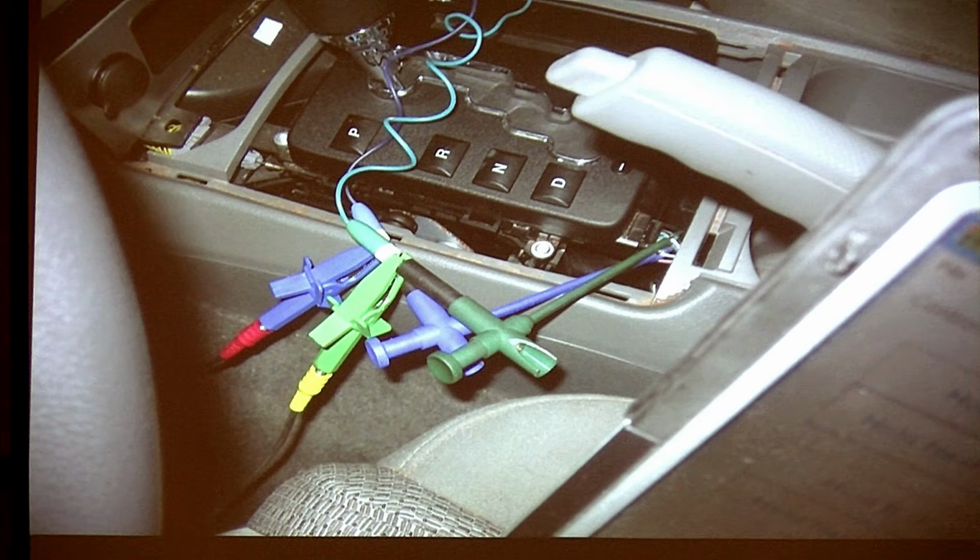So I'm going to take the same point of contact right here. I'm already in there, right, with my scope? And now I'm just going to run jumper wires, and I'm going to jumper them into where? The engine control module. I'm in the wires out there already, right? Guys, I don't care about twisted wires. I'm just trying to diagnose the car. I'm a flat rate guy. I don't have time to rewire and twist wires.